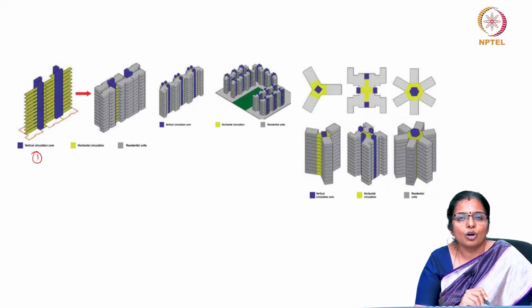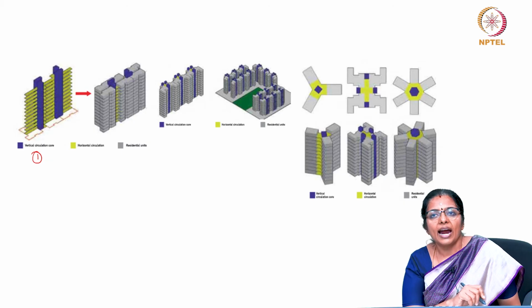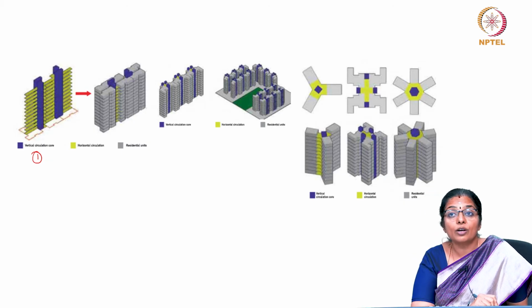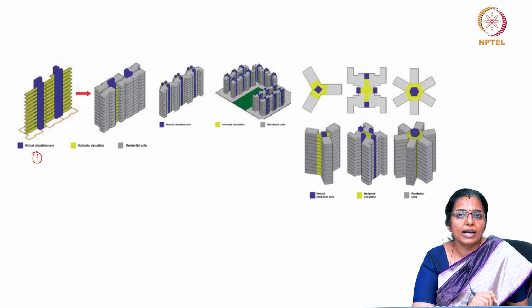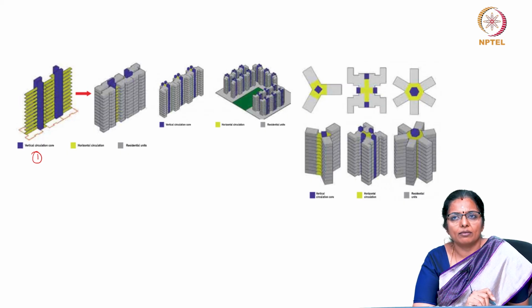The surface to volume ratio of the building should be as low as possible to minimize heat gain. Regarding the volume, the patio house is the most suitable form and can benefit in summer from the microclimatic effects of cool air pools that occur in courtyards. Although winter conditions in hot, arid regions would permit an elongated house design, the heat in summer is so severe that a compromise is required.